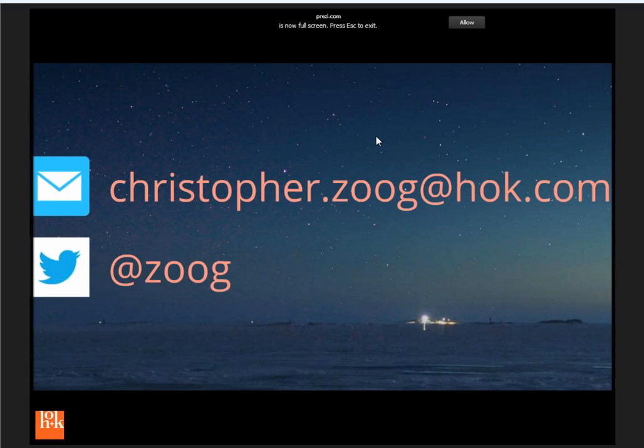But to me, really, what you're doing is what we need from you in the end. If you can suck in the Revit model and it helps start your design, the key is that you're going to move things around and put things in the right spot. We need you to get that information back to us, coordinated. All I ask of our sheet metal guys is an IFC file at the end of the day. One for model-based coordination, and more importantly for FM, because the owner wants an as-built of what's there.